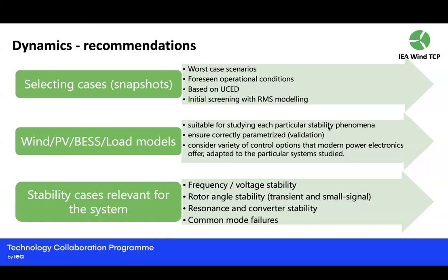So say a synchronous machine has so much inertia, so you count that if it's online, it brings so much inertia, and I have this constraint: do I have enough? But now you also need to model these inverter-based resources that are capable of doing that, and translate it into some kind of characteristic that you can put in unit commitment, so it counts towards this constraint. So this is all for you to figure out.